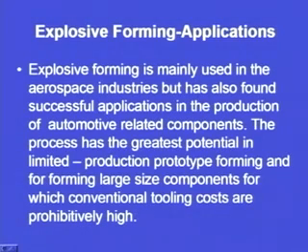Then what are the possible application areas of explosive forming? Explosive forming is mainly used in the aerospace industries, but has also found successful applications in the production of automotive related components. So, two important application areas are the aerospace industry as well as automotive components. Explosive forming is sometimes also used for cladding of plates. Sometimes when we want to join two plates, one a flyer plate and one a base plate, we use a continuous explosive and we can clad the plates.